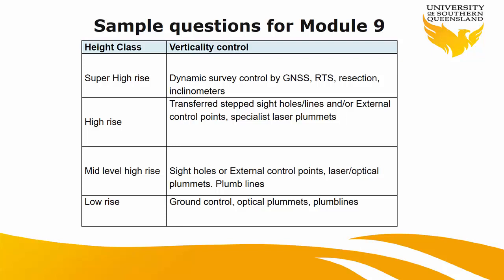And then we have high-rise and super high-rise. We use the GNSS system, and we told you the minimum is 3. Usually they use 4, to give a good configuration, to monitor the real-time changes using GNSS. This is pretty much the overview of what we've learned, and what might be in the exam.